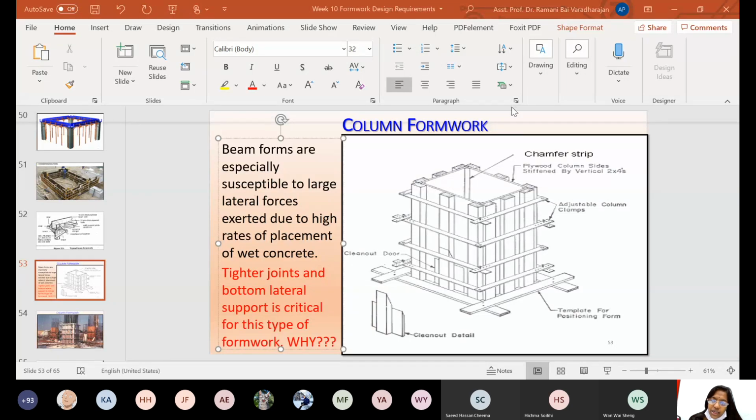Avoid delay, avoid finishing, right? Don't leave a smooth surface. There should be an uneven surface so that it will have a proper joint. The next part of the beam will be properly connected to the previous one. That is one thing. When you go to the site on training, you will know all these things. You have to see personally how they are doing it, right? Okay. So if you don't construct the joints properly, it will lead to lateral yielding, deflections, all those problems.